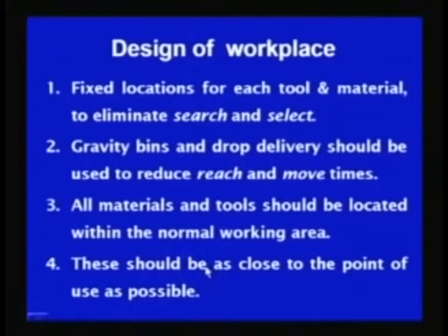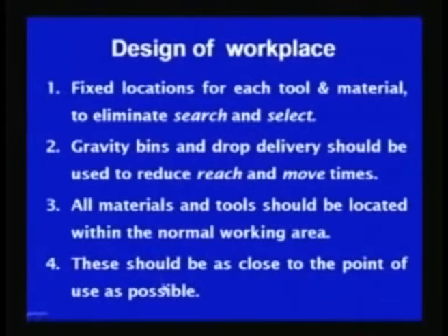The places for tools and work material should be as close to the point of use as possible, so that distances to be covered by the material can be reduced, and so that the fatigue of the operator related with the handling of the tools and the raw materials can be reduced, and the total time of the operation also can be reduced. So, if these are placed as close to the point of use as possible, it will reduce the operator's fatigue, and the time required for carrying out the job also is reduced.